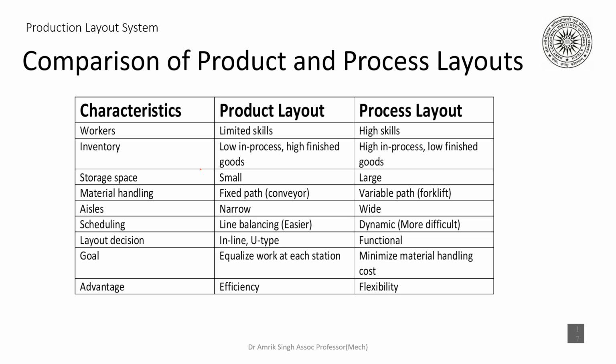So now if you compare a product layout and a process layout, I have tried to give you a comparison. When the workers are concerned, in the product layout we need limited skill, while in the process layout we need high skill. As far as the inventory is concerned, low in process and high finished goods. Okay. In-process inventory is low, WIP is low, and high finished goods because